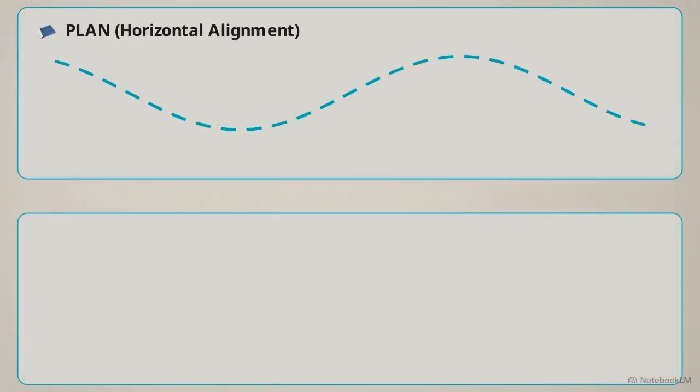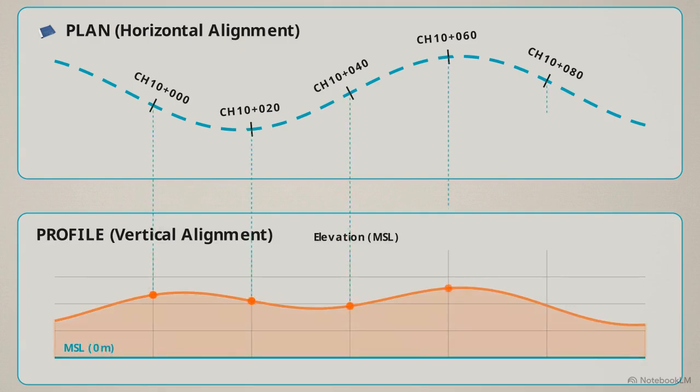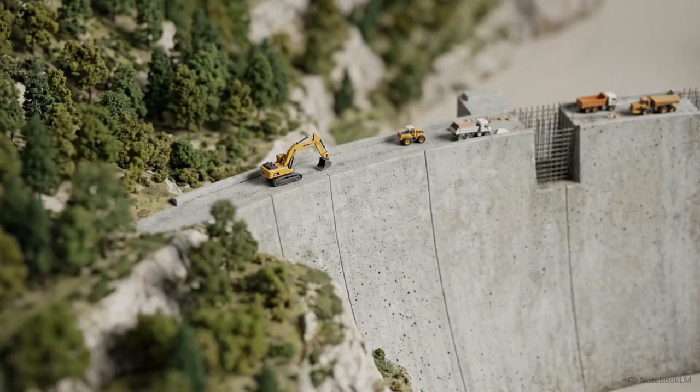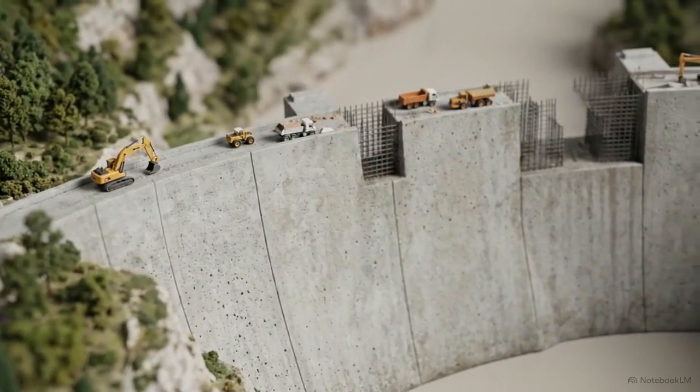For this top-down road alignment, linear progression is measured in chainage. Tick marks denote precise distance intervals along the centerline. Because infrastructure spans uneven Earth, it ties into global positioning. The bottom half maps elevation changes relative to mean sea level, matching the flat alignment. For massive load distribution, like sinking deep foundations for bridge piers, geotechnical data from borehole logs is embedded directly into these elevation profiles.